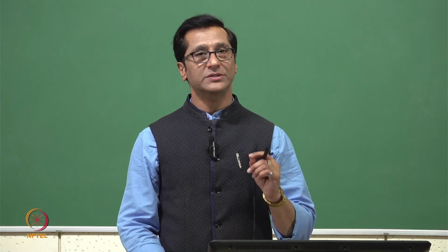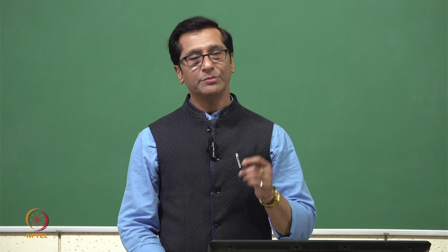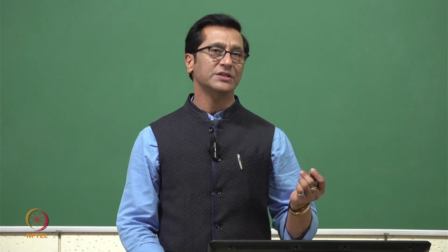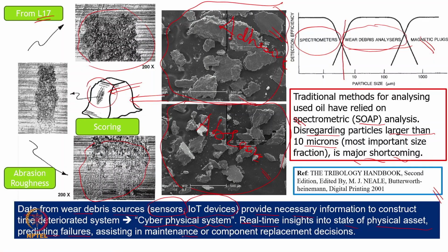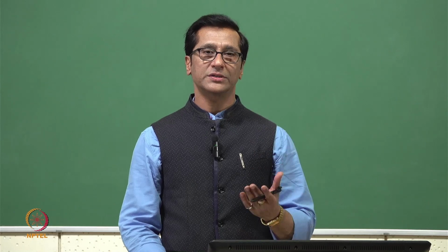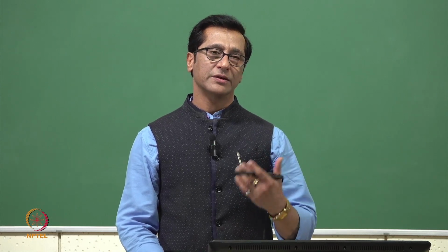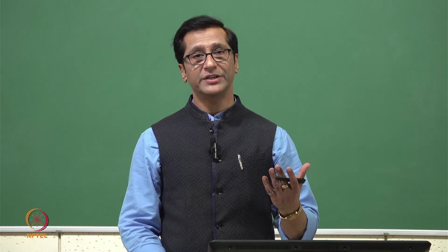As I say, resources are getting completely conserved, and we don't have to rebuild the system. The same system can run for years and years. So that is very important. It also gives us assistance in maintenance, and if we know that the system cannot be rectified and after 1000 hours we need to replace a component, we can order that component and replace it well in time, when the time to failure is indicated or predicted.